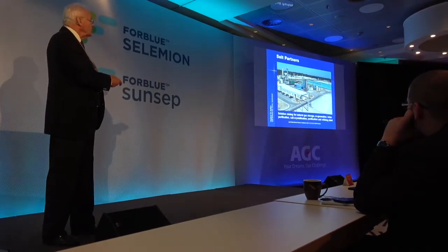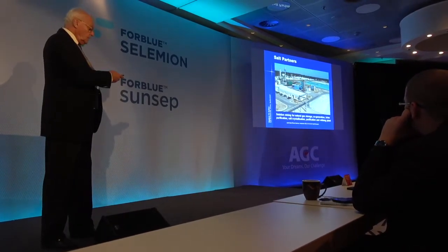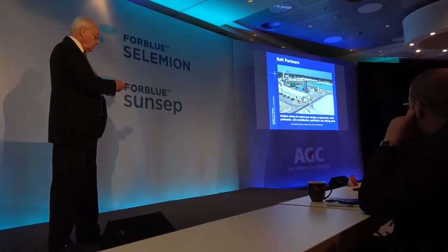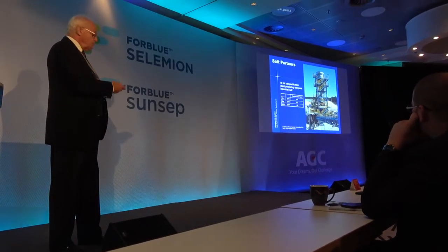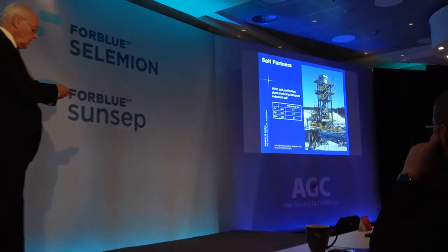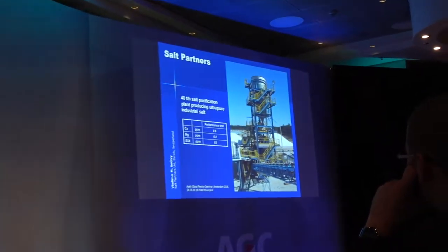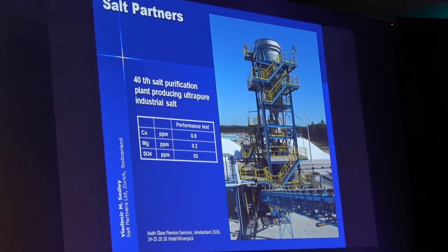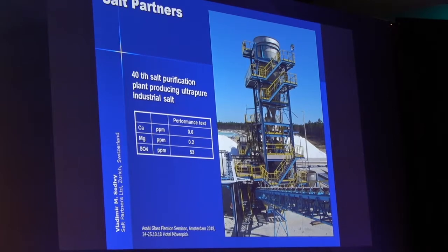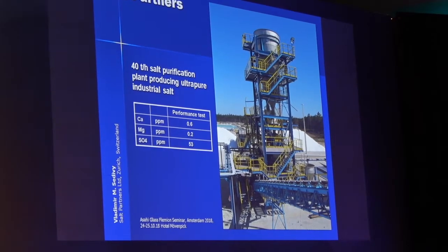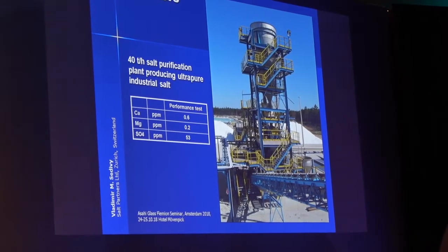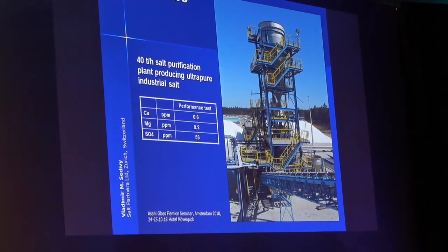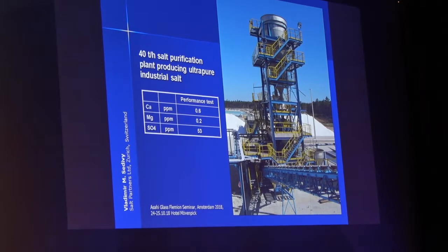These are the compressors. And we are harvesting the salt from time to time and purifying the salt in this plant. We are achieving purities of substantially less than 1 ppm of calcium and magnesium and 50 ppm of sulfate in that salt. So this is an example of what can be done without going for vacuum evaporated salt.